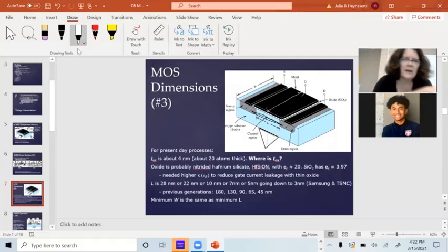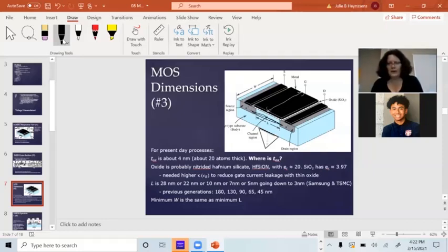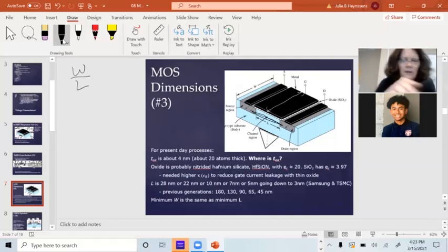And the key parameter you have as a circuit designer, if you're not the process engineer, to control the characteristics of the transistor is the W/L ratio. It's the only thing you can control. There are a lot of good reasons to make W bigger, but there are not many good reasons to make L bigger. In fact, a bigger L makes most devices work worse. So you want to get down to the minimum L you possibly can.